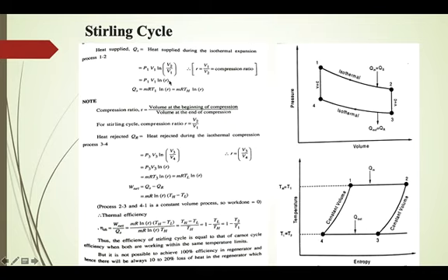So here we have a ratio V2 by V1. Now V2 by V1 represents the compression ratio R. Here there is a mistake in the slide. It is actually V2 by V1: on top it has to be V2 and at the bottom V1, that is total volume by clearance volume. This is true. V2 by V1 is actually the compression ratio R. So heat supplied is P1 V1 ln R, or m R T1 ln R. So this is the expression for heat supplied.